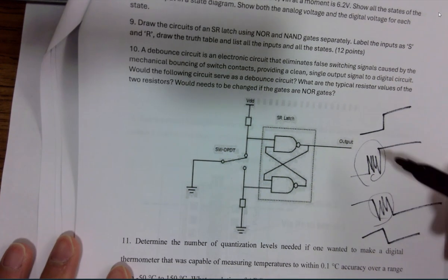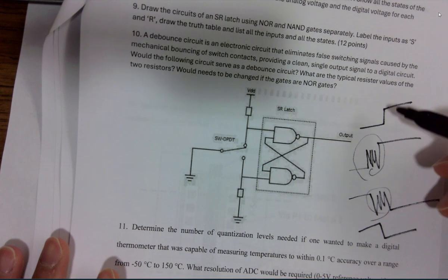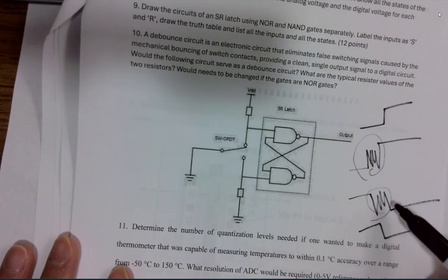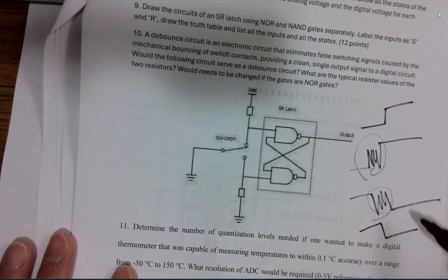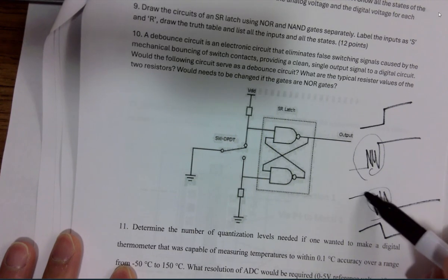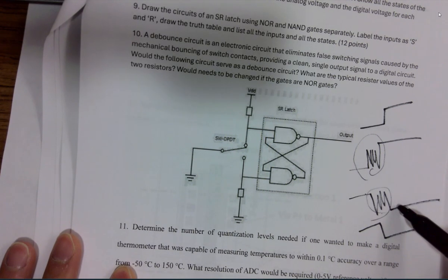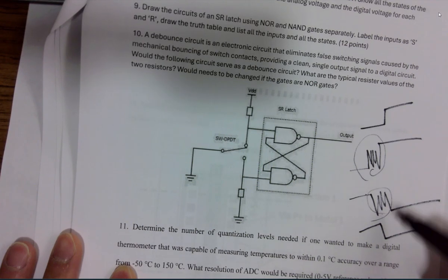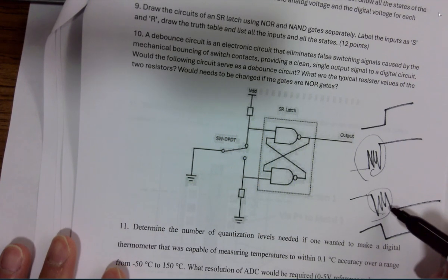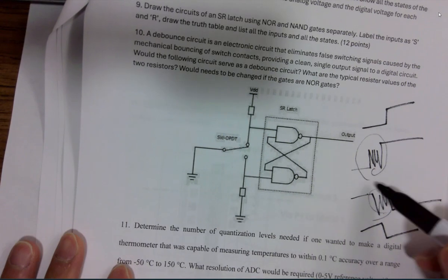You can imagine in your microcontroller loop, if you don't put debounce software in there, you are just detecting, hey, when this is 0, do something. However, it keeps coming back and forth and gives you so many different zeros, and you wouldn't be able to know when it got started, right?